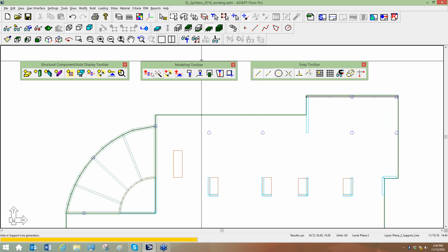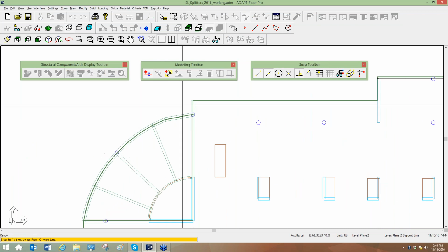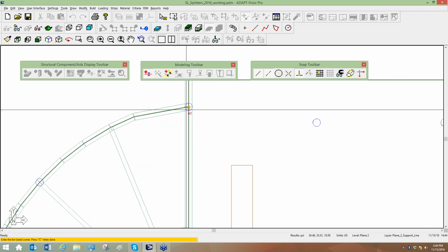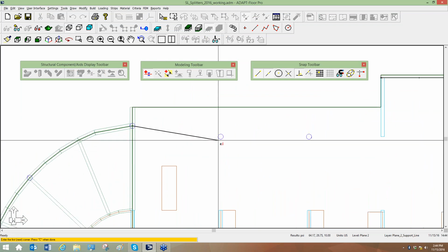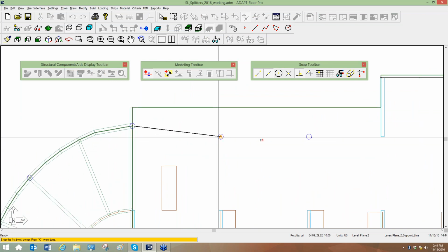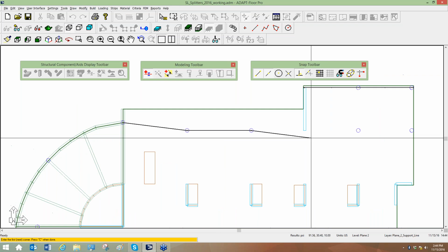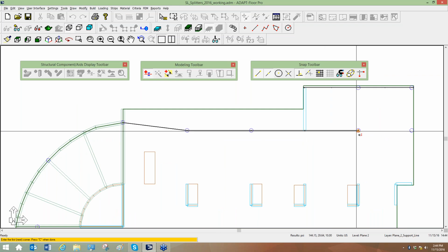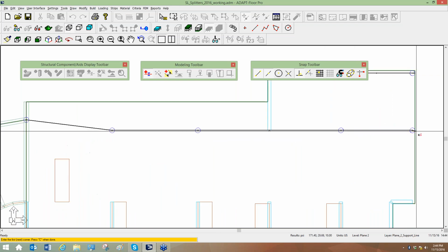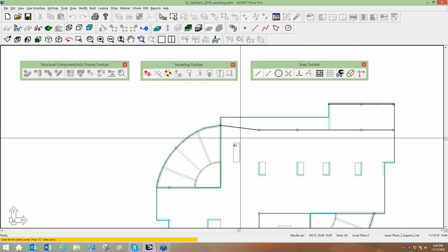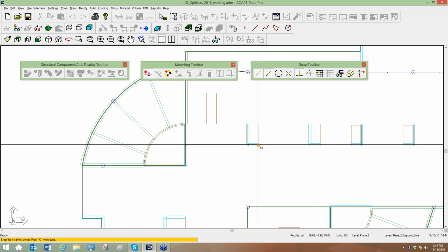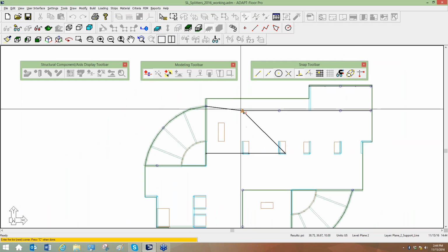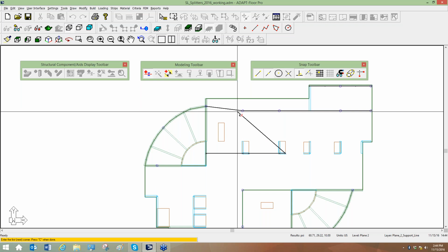Okay, I'll go back. Now, remember, I'm going to ignore these areas, these curved areas out on the outside. So I'll go from this support down to here, and as I'm doing this, I'm going to explain a couple of things. The rebar follows the direction of the support line. So when the program generates reinforcement, it's going to follow this support line, so parallel to it.